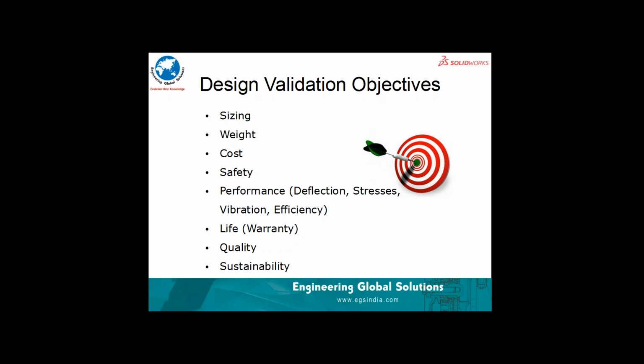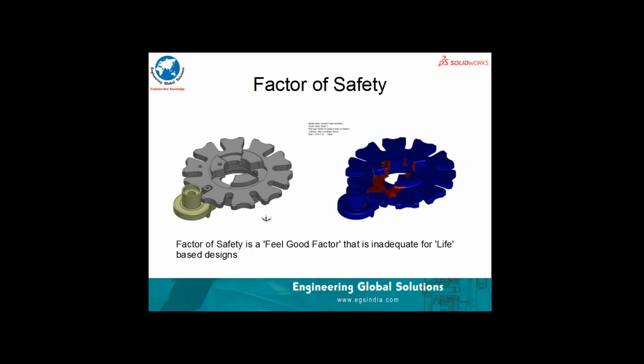Necessarily, these have to form a part of the checklist that we put together before a drawing is released for prototyping or tooling. Normally, we look at the factor of safety. The factor of safety is actually a feel-good factor. It is not adequate when it comes to life-based designs.